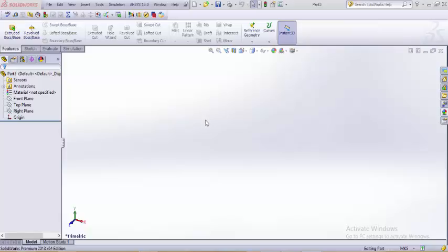So for some introductory information, let's see why I-beams are made. I-beams are made usually to maximize the usage of materials, and in solid mechanics, structural mechanics analysis, it is found that the maximum bending stresses are at the two edges of a beam.